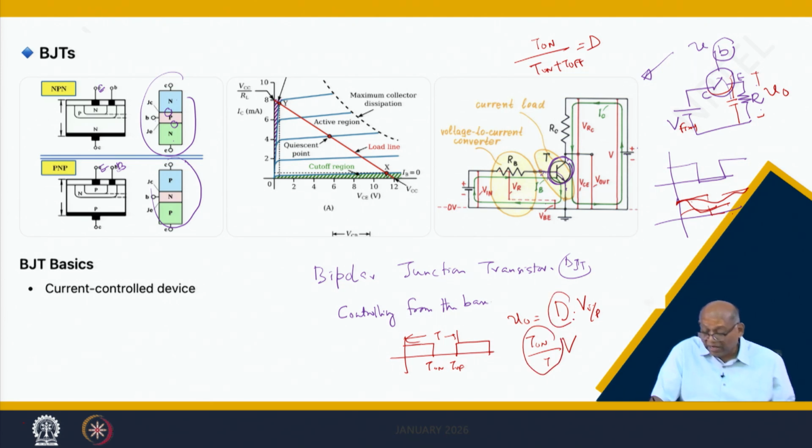So by changing the on and off time, you can adjust this, and if you put a capacitor across this, it will also be filtered and become smooth. You can control it by switching the base input on and off with low power electronics. So this is the first control, but BJT is not used because of a lot of heat and current control. This is the BJT characteristic.